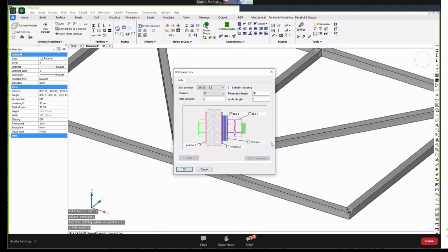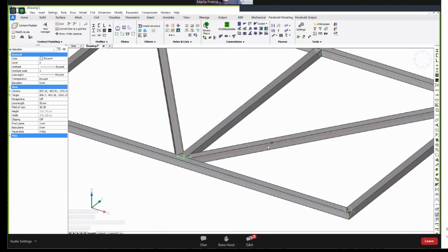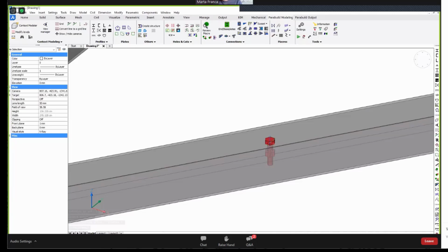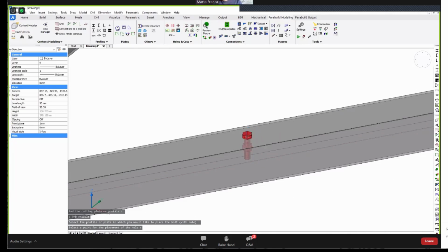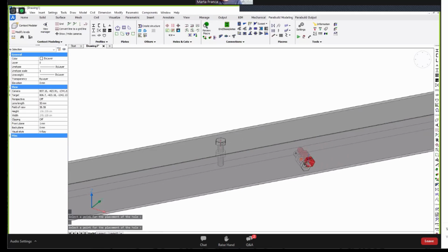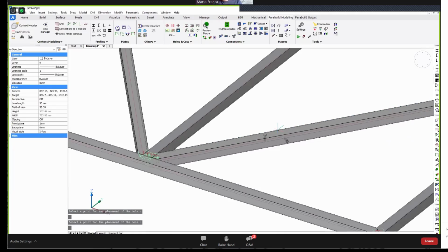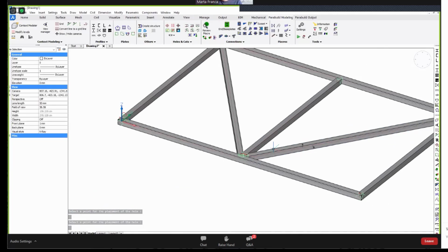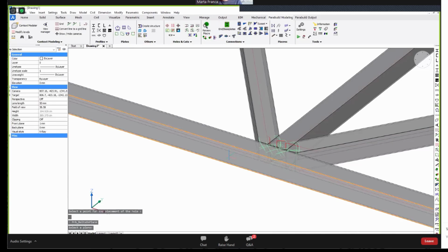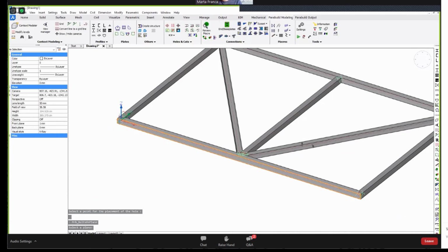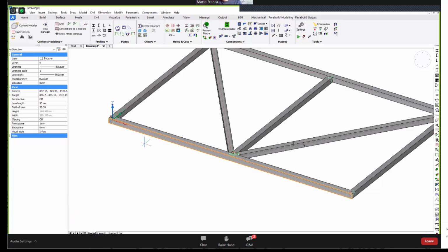just select the part that should receive the bolt, and you can draw a bolt there, but the downside of this tool is that you need the exact coordinates. So this is not necessarily the best tool in all circumstances. So for that, there is here a very practical tool, bolts on a plane. And if I just select this side face of that SHS profile,